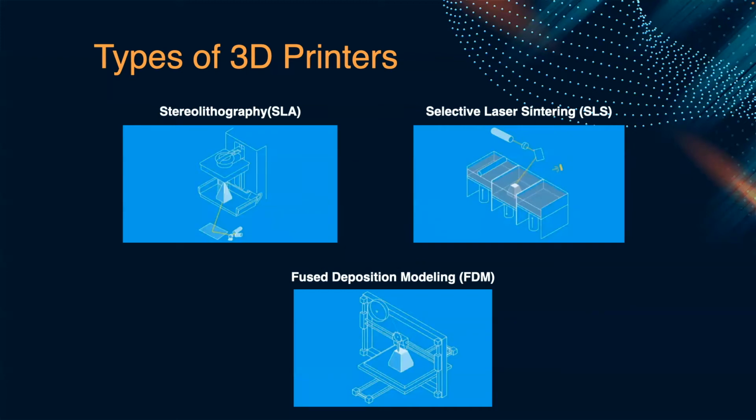FDM 3D printers are well suited for basic proof of concept models, as well as quick and low cost prototyping of simple parts, such as parts that might typically be machined. However, FDM has the lowest resolution and accuracy when compared to SLS or SLA, and is not the best option for printing complex designs or parts with intricate features. Higher quality finishes may be obtained through chemical and mechanical polishing processes. Industrial FDM 3D printers use soluble supports to mitigate some of these issues and offer a wide range of engineering thermoplastics, but they also come at a steeper price.